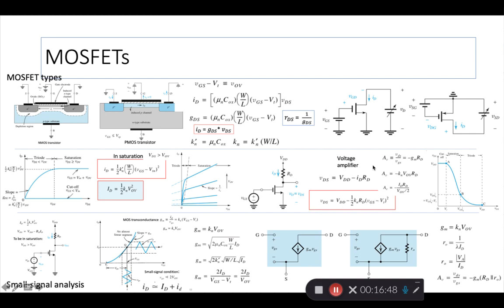So that brings us to the question of voltage gain, right? Voltage gain we define as the output voltage divided by the input voltage, or actually the change in the output by the change in the input. And there's a number of ways to calculate that. Here we only use the known constants like Kn and overdrive voltage and the RD. Same thing here.